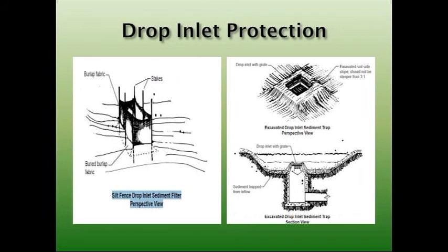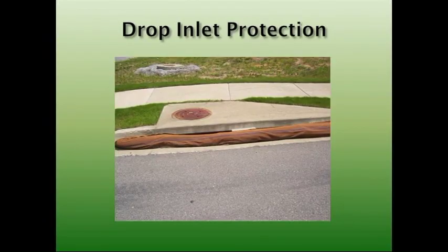Or you have this. You see a lot of these with the silt fences on 4 corners. Just make sure if you do this, you support this with wire mesh, because otherwise it'll fall in on itself. There's an inlet protection with the bags. You can use those. It's kind of a plastic material. I'd never seen one of those before we went out there.